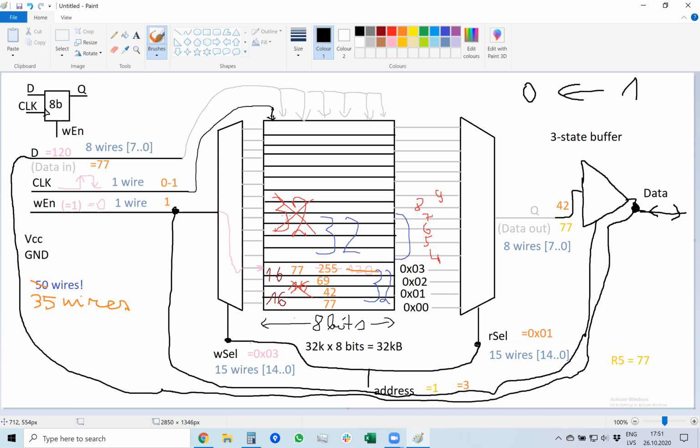As you know, the output of this thing is these two MOSFETs, so the output is push-pull MOSFETs. Either they connect the output to the power supply, or they connect it to ground.